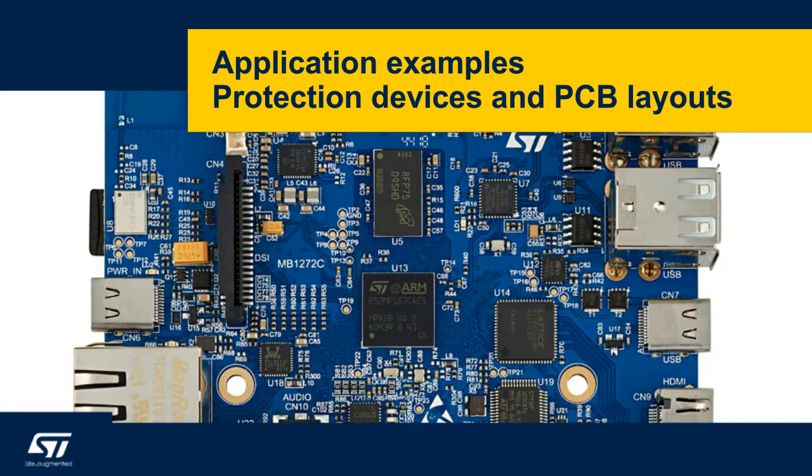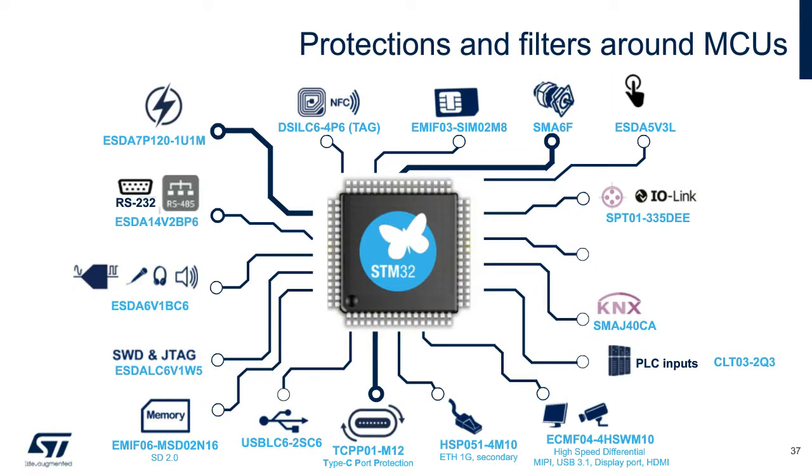The application core product is usually a microcontroller. It features many peripherals which are in the final application naturally exposed to the surrounding environment. As an example, we all know many different communication buses like USB, RS-232, Ethernet, with their connectors accessible to the outside environment. We also have audio connectors, slots for memory cards, or just a simple push button in our applications. All of these peripherals should be protected in an ESD robust design. Let's go now through several concrete examples.